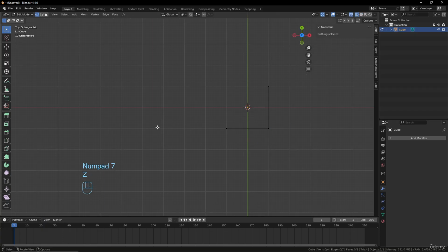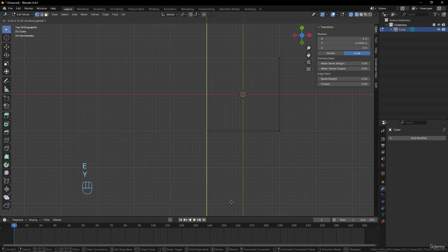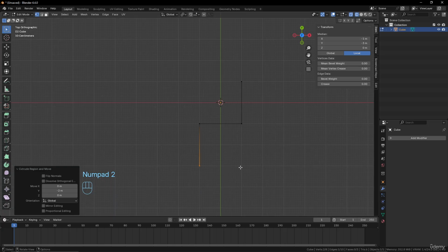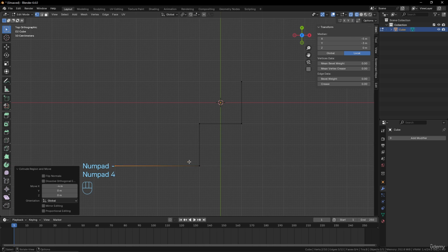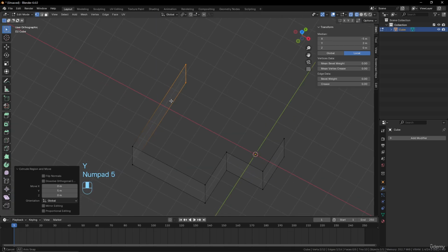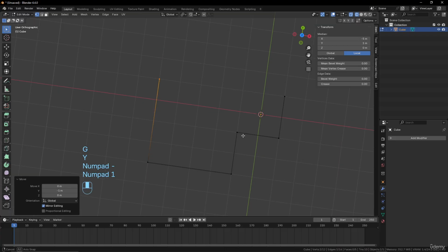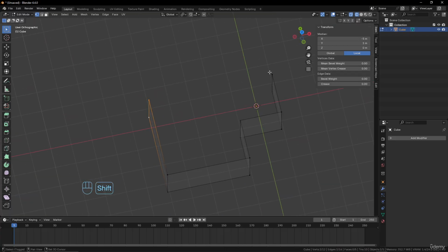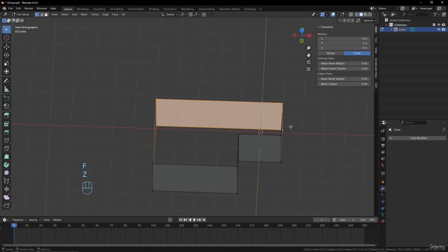Here I have my shape, and I would like to extrude it on the Y axis, maybe -2, to have something like this, and extrude on the X axis -4, so 4 meters here, and extrude it on the Y axis 5 meters, and maybe -1 like this, and I will create a kind of room shape, okay, just by creating this.